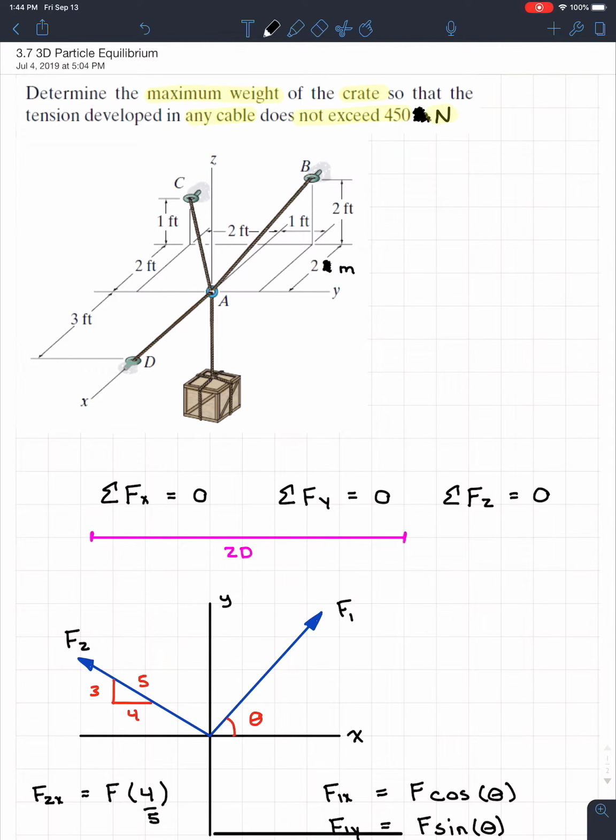everything. The 3D can look exactly like this. For example, they could also maybe, from A and B, put a spring here. The same concepts still apply. The hardest part about 3D now isn't really knowing the tricks, but getting the components of each of the forces, because three-dimensional forces, of course, are going to have 3 components. So I'm just going to erase this because we're not dealing with springs here.